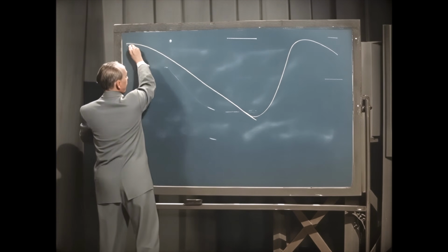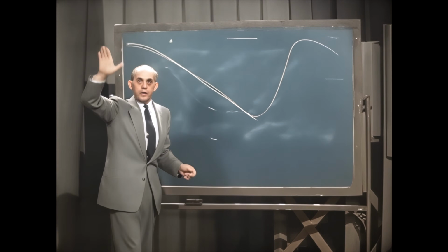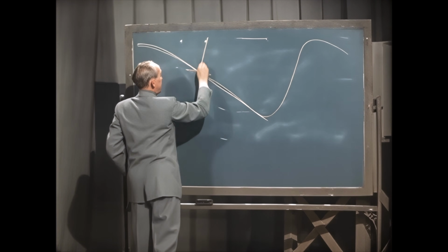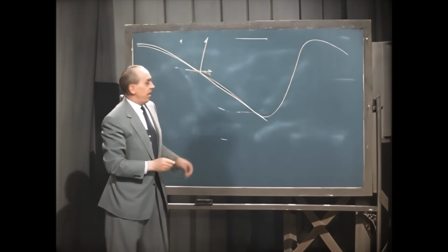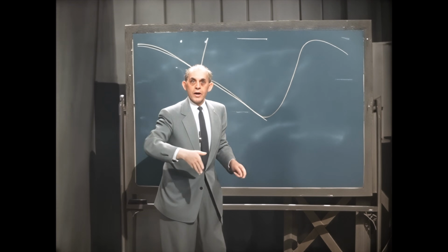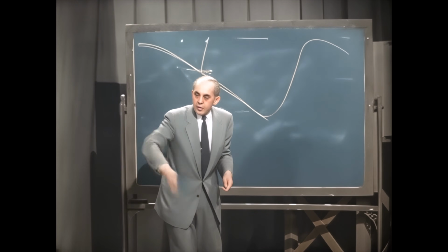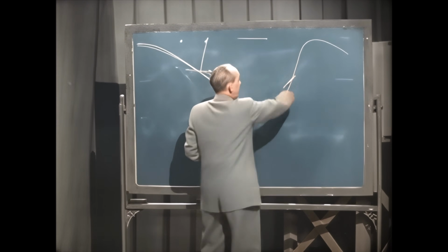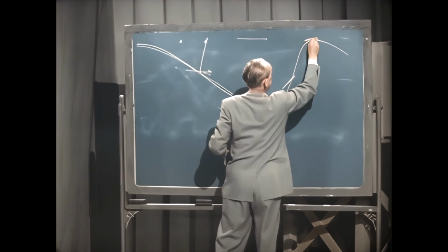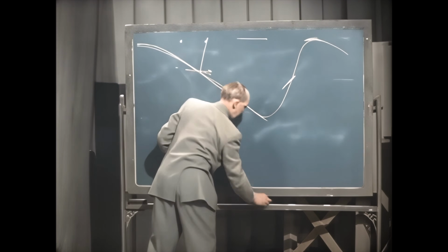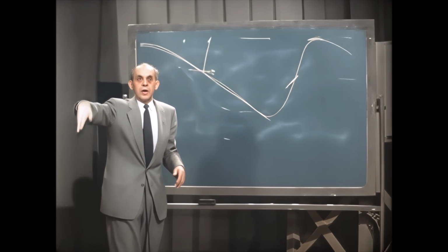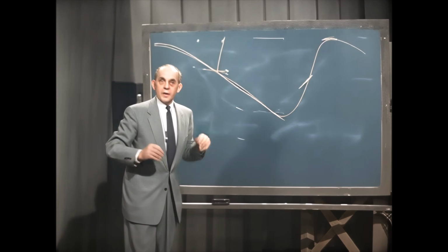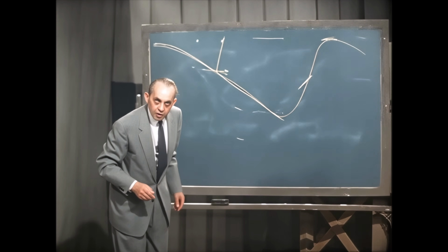And while you have the downstroke, you have all the velocity which is needed to make the lift and forward thrust. In the upstroke, you have practically no speed because you pull the wing backwards. And in this way, this wing is brought into its working position in the downstroke by the most efficient way and the way where the drag is the smallest.